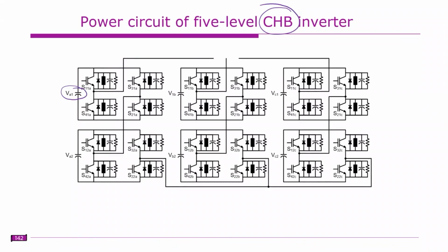Sir, cost wise, which is better compared to dSPACE and FPGA? FPGA is cheaper when compared to dSPACE, but in the case of FPGA, there are a lot of models. Based on the clock speed of the processor, the cost will vary.